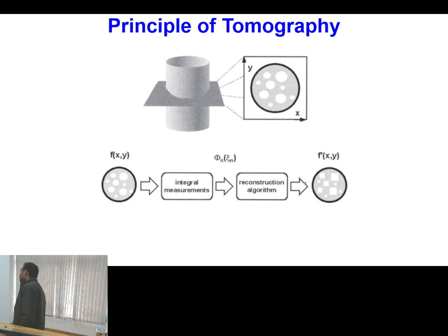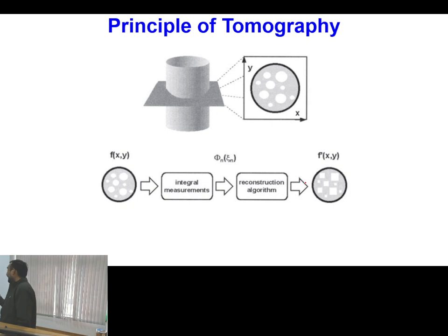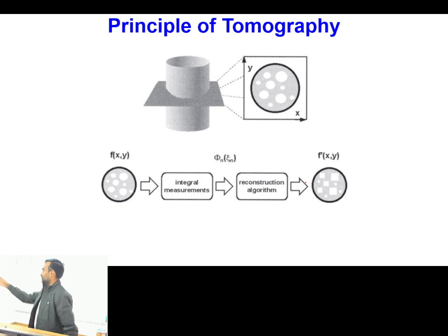Basically, your measurement technique does not know the actual nature of the fluid. These are just based on the data you are providing. So you know that if this much value of capacitance is observed, this is for water, so you can tell that this is water. But that will be simply telling that for this we have this much capacitance, and for this we have that much capacitance. Depending upon your understanding of the phases you are flowing, you have to decide that for this value, this phase will be water and this phase will be kerosene or gas. Okay.